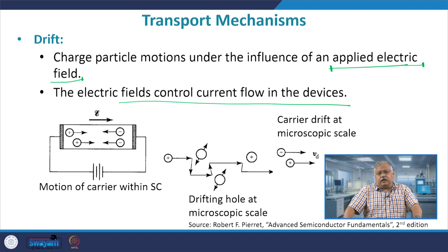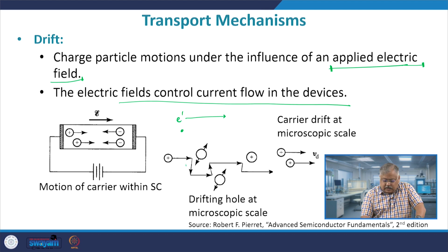However, when you look at electron drifting in a material, obviously these electrons will not be drifting in a straight line. They will always drift such that there will be multiple scattering with the ions and with the particles of the device itself. And when it does that, it starts to scatter from its mean position, right? So when it scatters from its mean position, its mobility drops down, right? And scattering related mobility is always available to us. The higher the velocity, the more is the probability of scattering, and therefore the lower is the mobility which you will get.